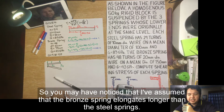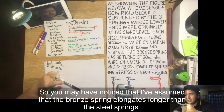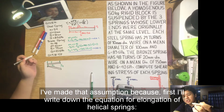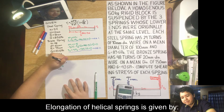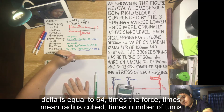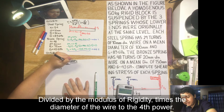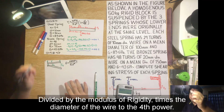So you may have noticed that I've assumed that the bronze spring elongates longer than the steel springs. I've made that assumption because first I'll write down the equation for elongation of helical springs. Elongation of helical springs is given by delta is equal to 64 times the force times mean radius cubed times number of turns divided by the modulus of rigidity times the diameter of the wire to the 4th power.